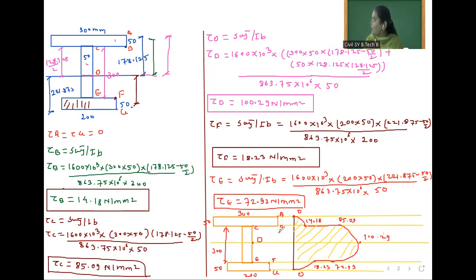Section, then at top and bottom there will be zero stress so minimum steel is sufficient, but shear stress at the depth of the neutral axis is maximum, so here steel reinforcement is maximum. So for this we are calculating.